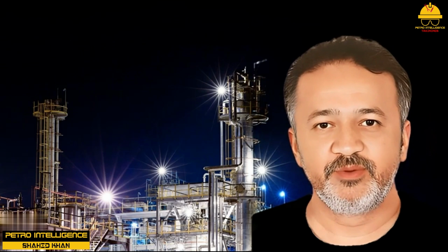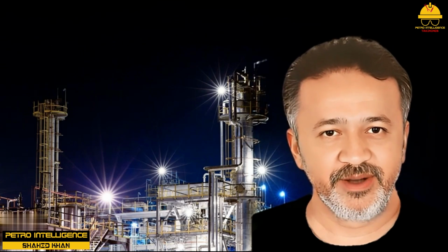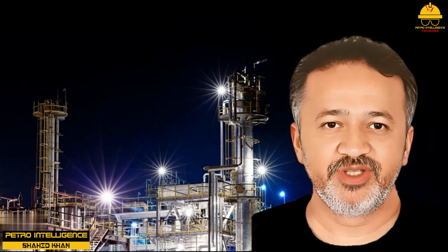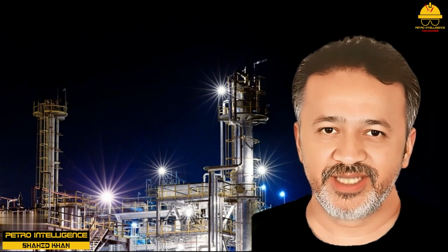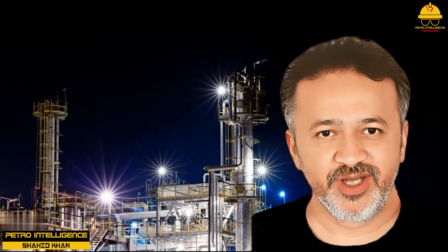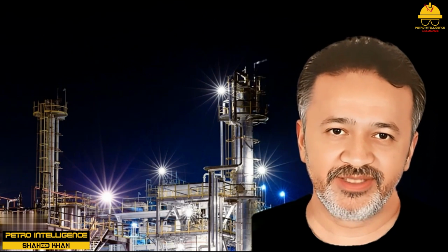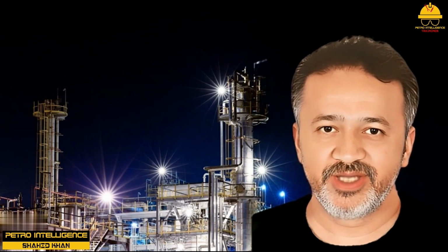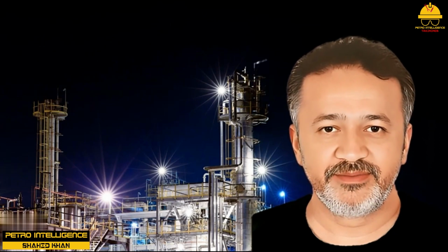The choice of the method for heating or cooling the reactor must be made in the design phase. The basis for such a decision is concerned with: 1. The availability of steam, brine, cooling water, and the like; 2. The temperature at which the reaction must be controlled; and 3. The cost of each method per pound of production.